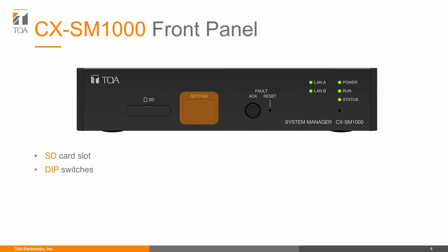In the event the device detects a fault, there's a fault acknowledgement key to make the buzzer stop, and also the status LED will stop flashing. If you want to reset the fault manually, you can do this with the fault reset key. You just need a small object about the size of a paperclip to press and reset the button, and you're good to go.